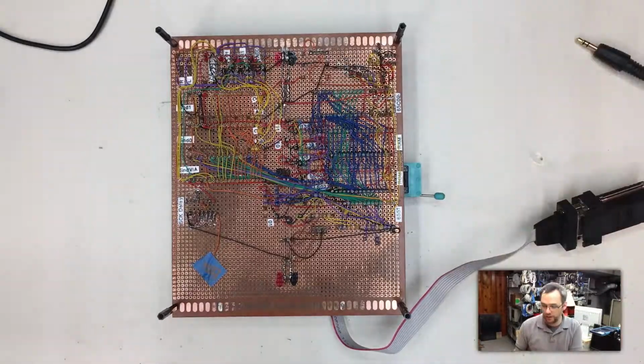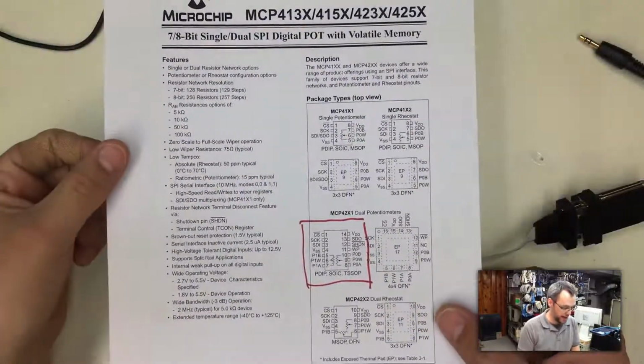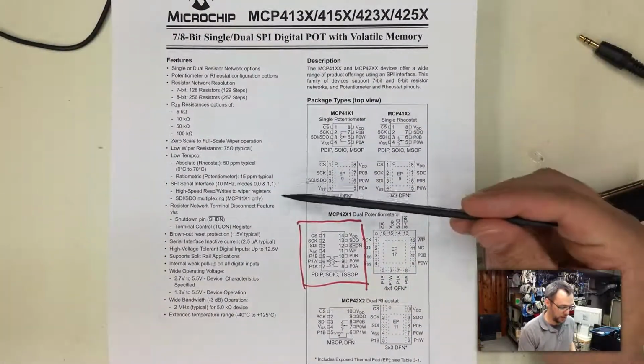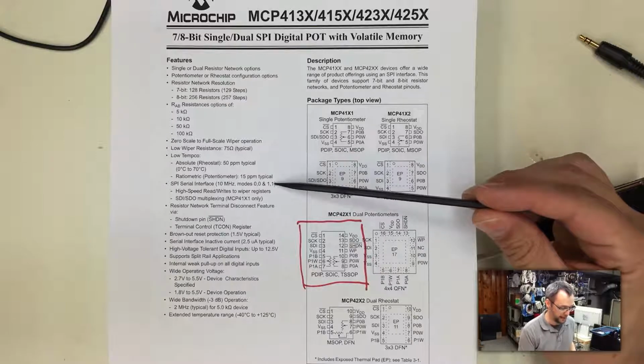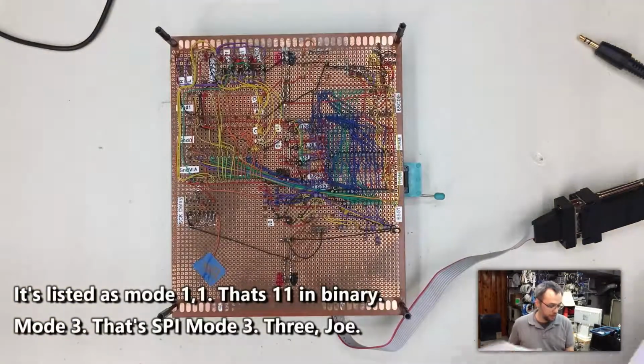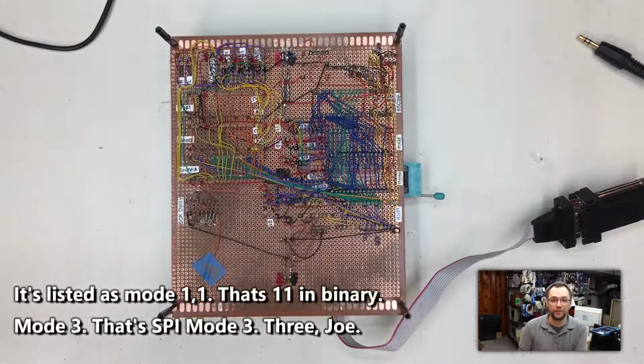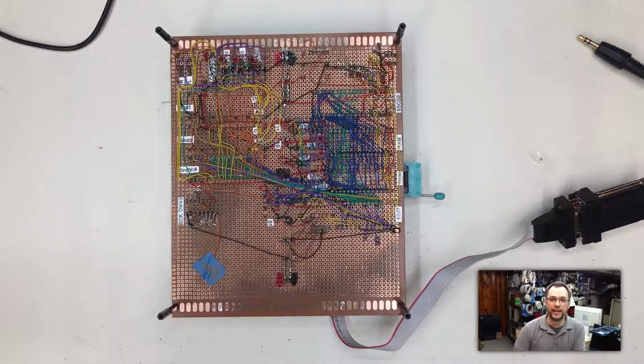However, if we look very carefully in this document right here, you can see that this chip supports SPI mode 1. So that means because it supports SPI mode 1, I can connect my clock and my data directly to those chips and just send the data out, and the chips will pick that data in and just use it.